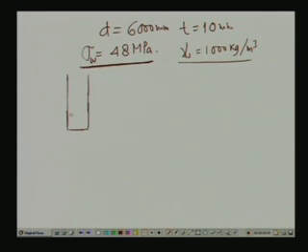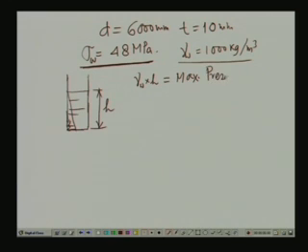As the water level is going up, say up to level h, the maximum pressure exerted by the water is equal to gamma W times H. So, we have to compute the value of the stress with reference to this maximum pressure, so that the maximum stress can be evaluated in the tank, and corresponding to that we can find out the height. Corresponding to the maximum pressure, the maximum stress will be generated, and of course, as the pressure reduces, naturally the stresses at different points will be different.